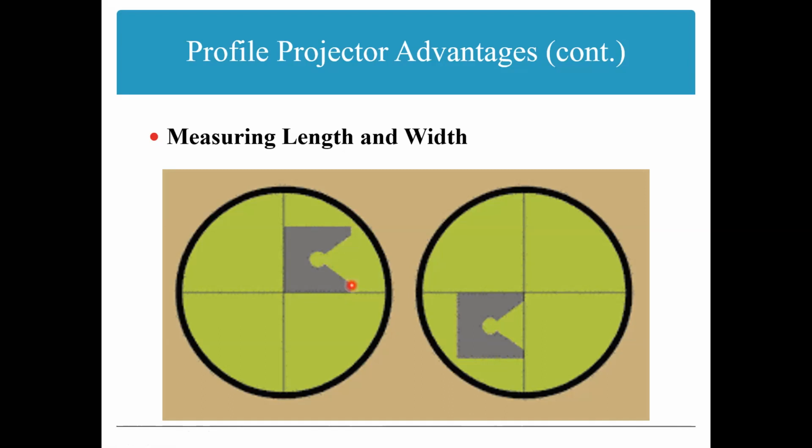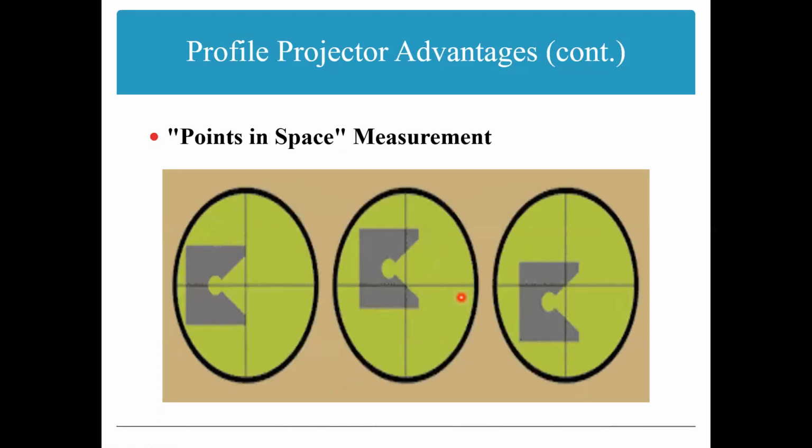And also, this profile projector can be used for point measurement. Suppose if you want to measure the pitch, in that case, you have to take the distance between two points and the corresponding teeth. In this case, the point measurement is also possible by using this profile projector.